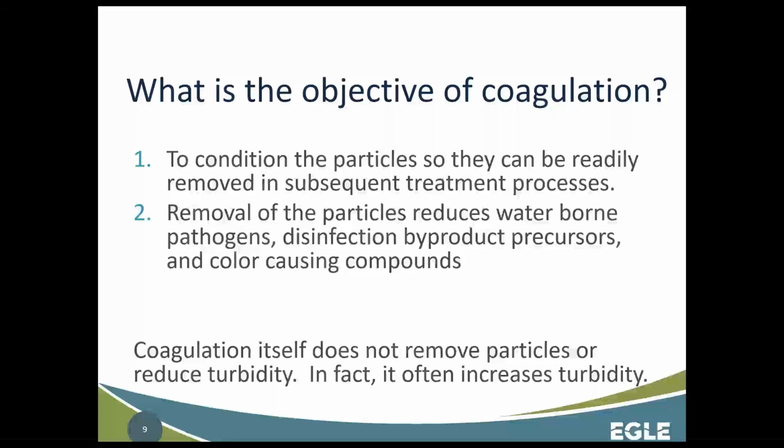So I think there's a few things here. Coagulation is just a conditioning process. It doesn't do anything to remove particles. And in fact, we don't want particles to be removed in the coagulation area. It's not designed generally for frequent removal of particles. So if you start getting particles building up in between your rapid mix and your flocculation area, that could be a maintenance issue. And also, it's probably not going to produce the type of flock that you're looking for if it's already forming up and falling out of suspension immediately after the rapid mix.